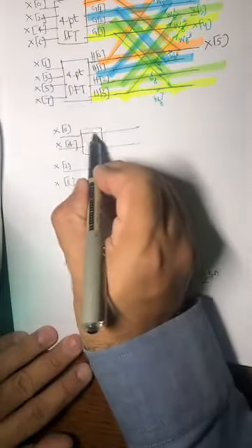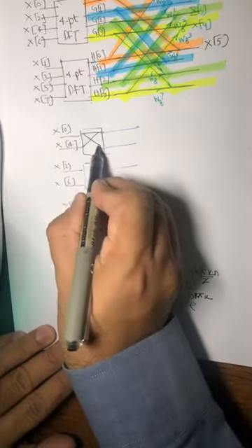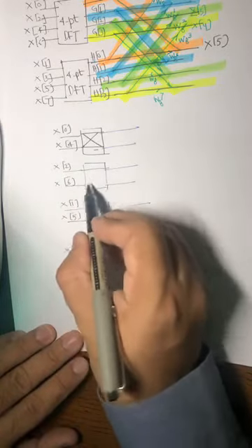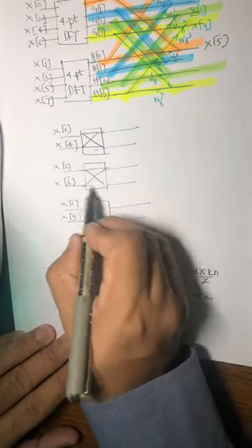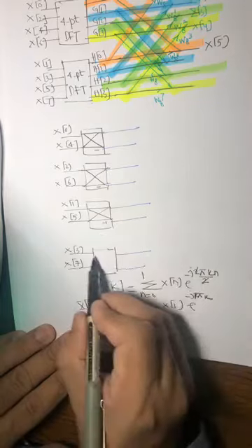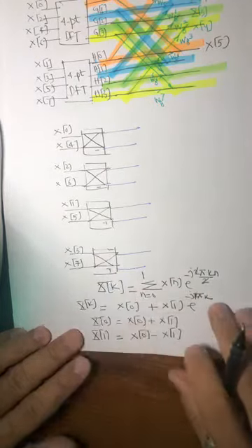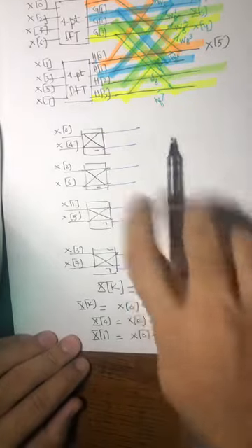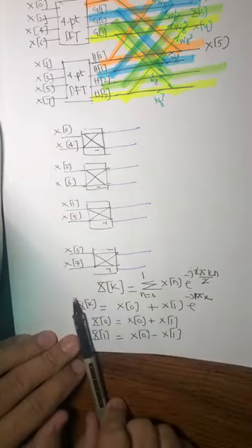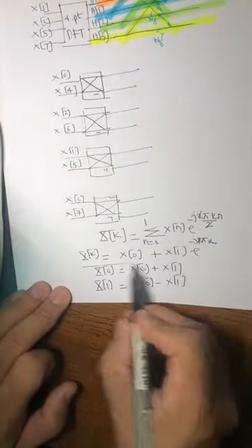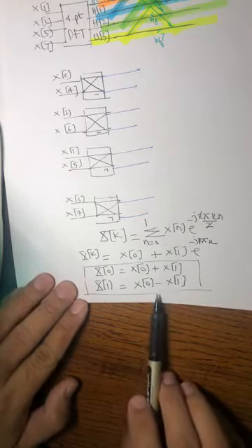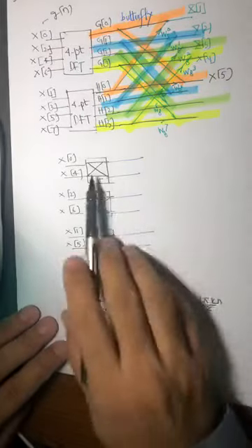You add these 2 samples together and you subtract these 2 samples together. Add these samples together and subtract these samples together. Add these samples together, subtract these. This is all you have to calculate actually. Adding, subtracting, first splitting it, no matter how big a signal you have, into 2-point DFTs. And 2-point DFTs can be calculated in a very simple manner, because the formula says a 2-point DFT is once you add and the other time you subtract. So you add, you subtract, you add, you subtract.